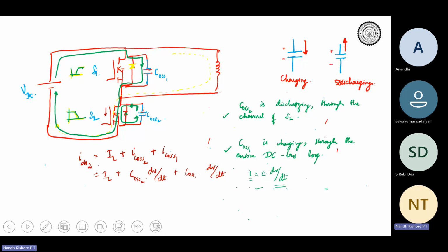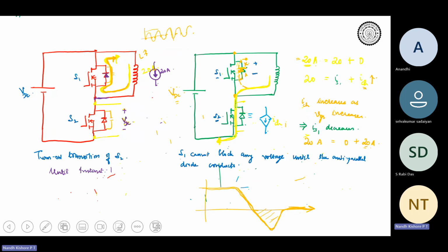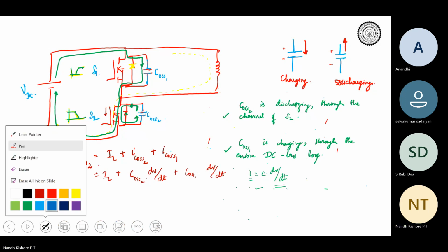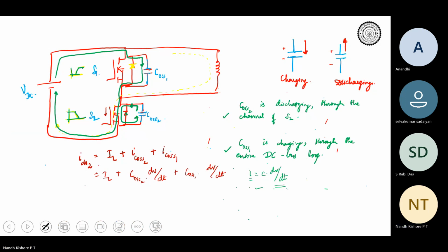Yeah. So it is actually a positive current between cathode to anode, right? The reverse recovery. So this is your QRR, right? So this reverse recovery current, you will see this reverse recovery current will also flow through the devices too. Okay. So the reverse recovery current, let me start from here. The reverse recovery current will also flow something like this.